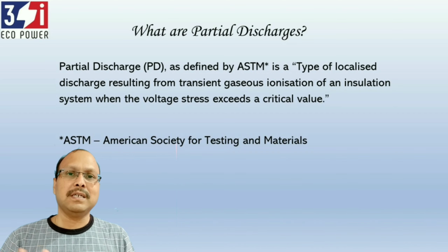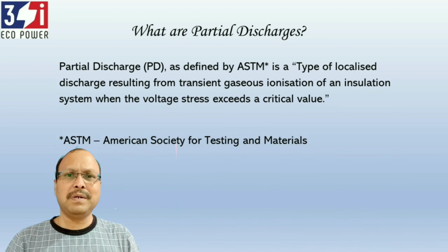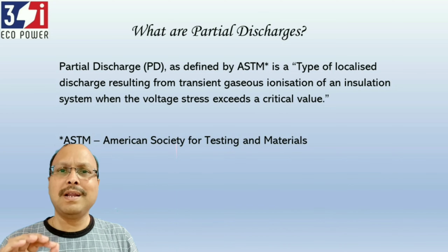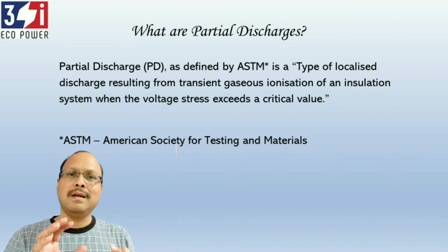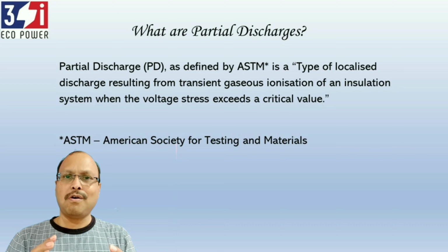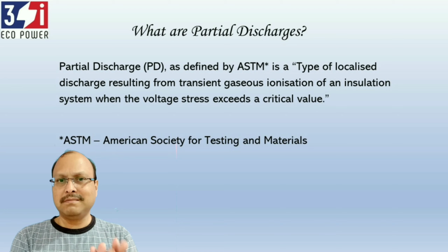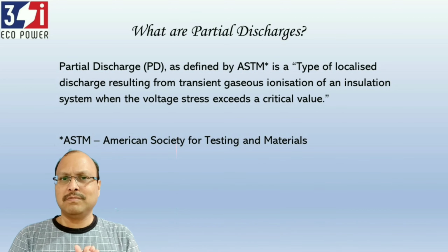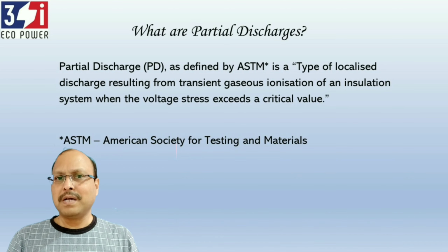According to that definition, it is a localized discharge, the name discharge itself is there, because of transient ionization of the insulation system whenever there is a variation in voltage levels. The details I will tell further, but this is broadly the definition, and the exact definition you are viewing on your screen. So this is what a partial discharge is.